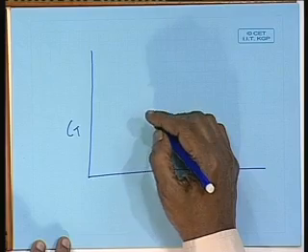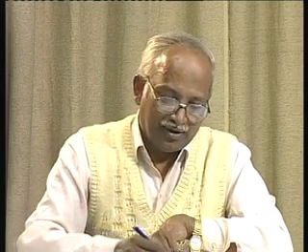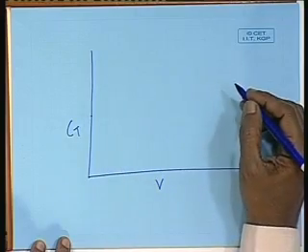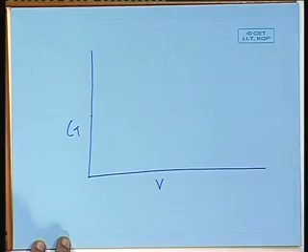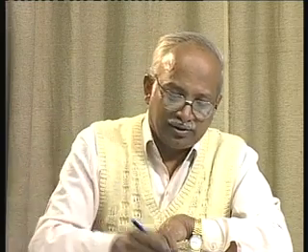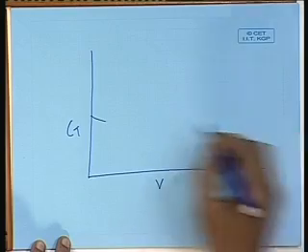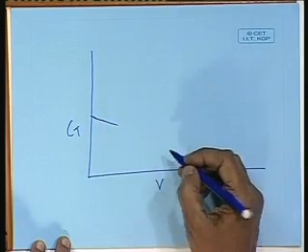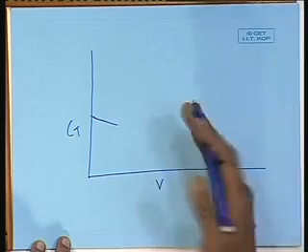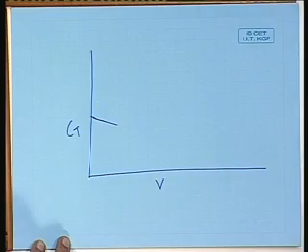There will be frictional resistance coefficient, will it be there or not? Yeah. So, we will have a frictional resistance coefficient which will reduce as speed increases. Am I right? Because Rn will increase and in the ITTC formulation, if you remember, Rn is in the denominator. So, the frictional resistance will diminish for a speed corresponding to Froude number 0.1 or 0.15, after which wave resistance will start taking off.